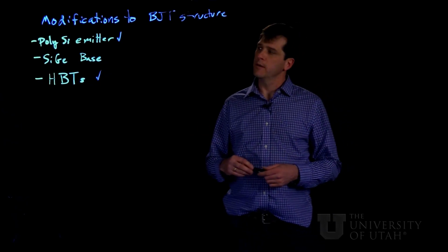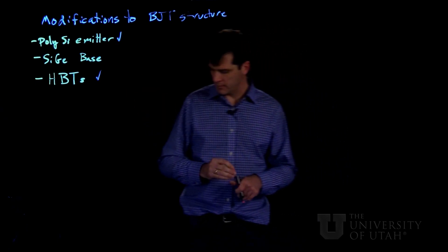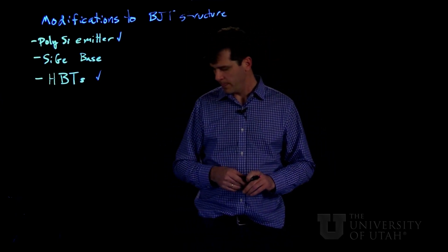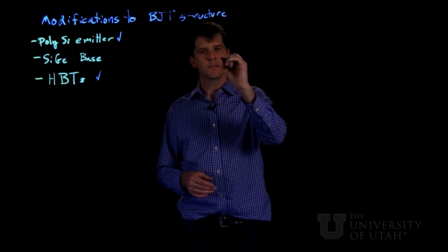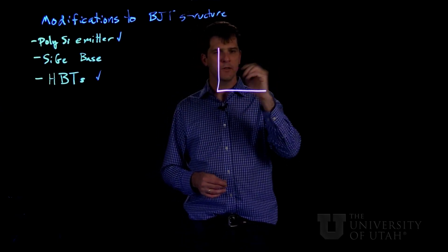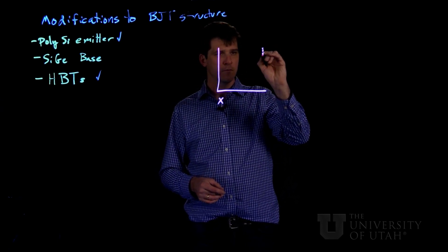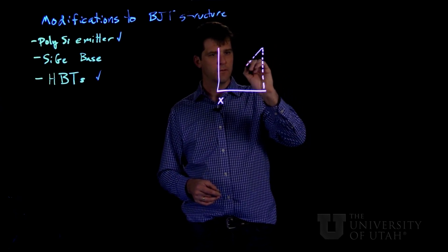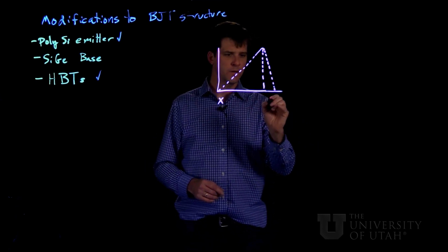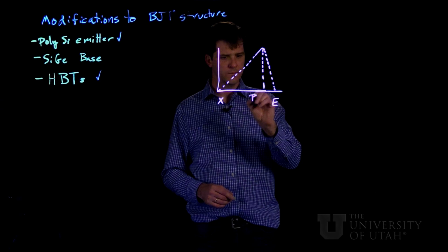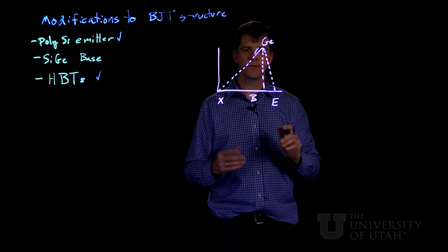Okay, for our final topic and subtopic, let's go back to the silicon-based BJTs, and let's look at what happens if we put some germanium into the base. So we're going to imagine that we can construct the base with some germanium added through the base and a little bit into the emitter. So this is our germanium. So it has to be non-uniform in this design.